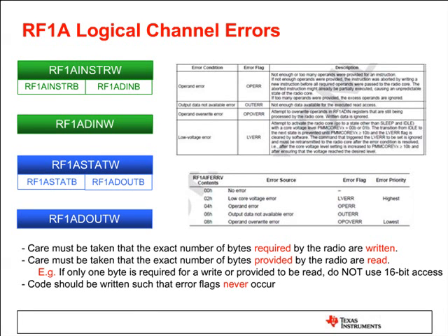If you tell the radio you're going to provide a piece of data, but you don't, and you just write another instruction, you're going to trigger an error. Or sometimes the radio is doing some kind of calibration on its way to transmit mode, right? And you start providing data to the TX FIFO.